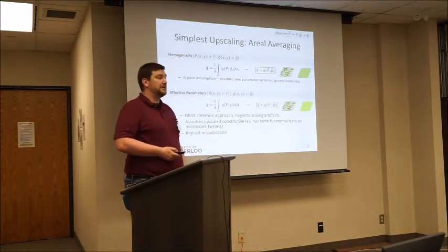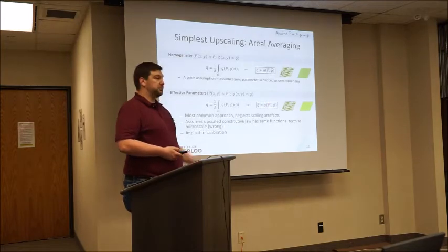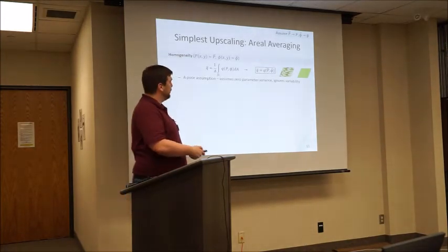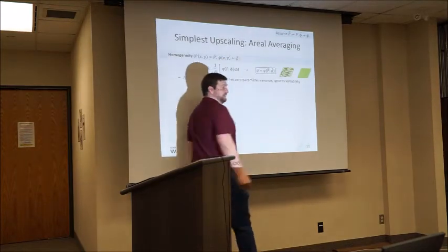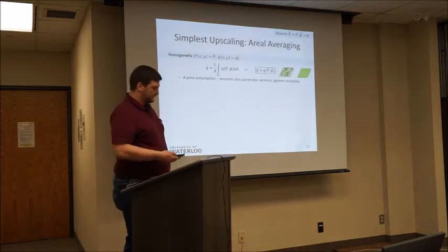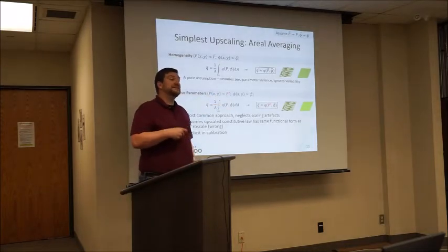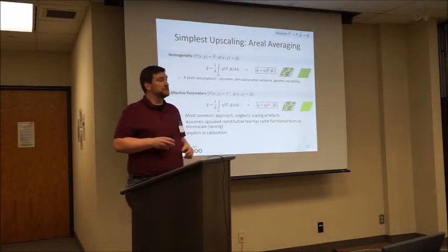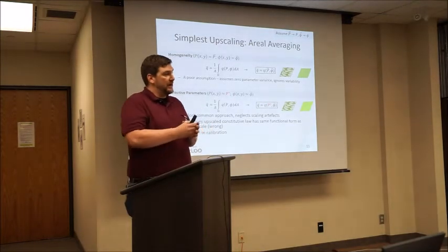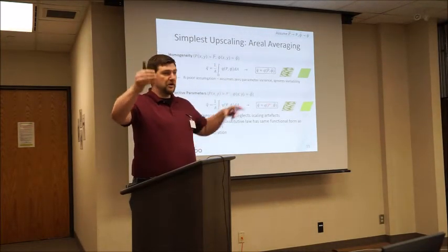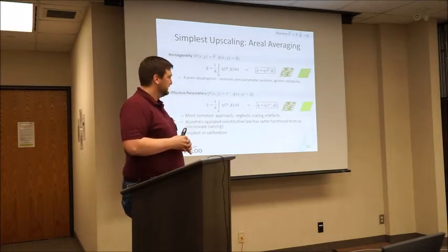So, next step we can go to is the process of effective parameters. We're going to say that this is not right because it ignores all of the interesting stuff in the middle. So next step, we go with effective parameters. And this is what most calibrated, physically based models are doing. They're applying Richards equation over a 100 meter by 100 meter parcel in a heterogeneous landscape.